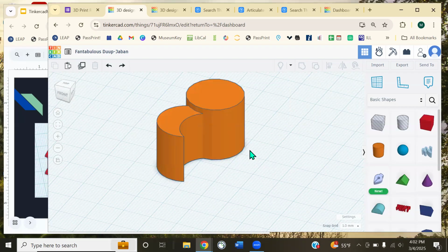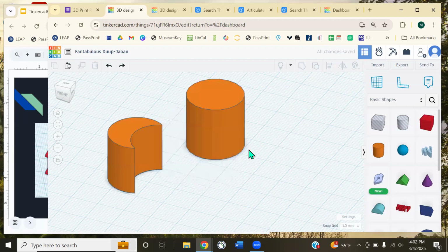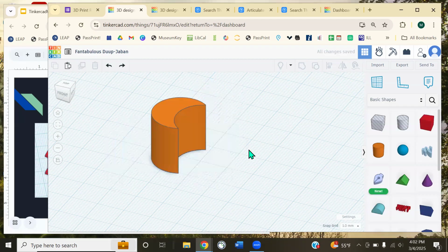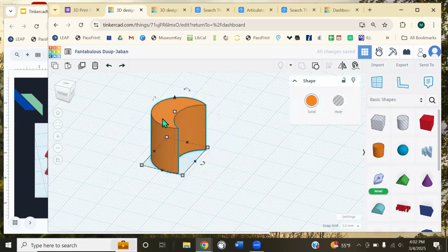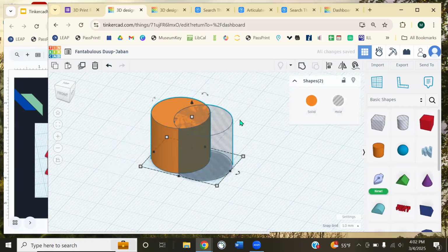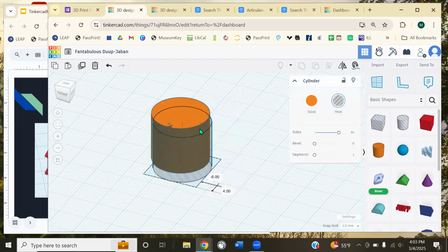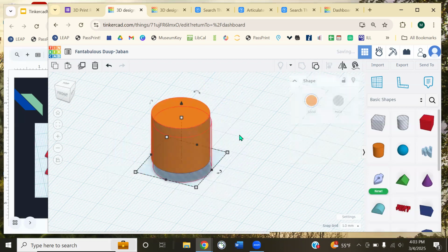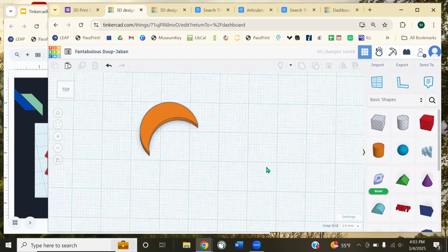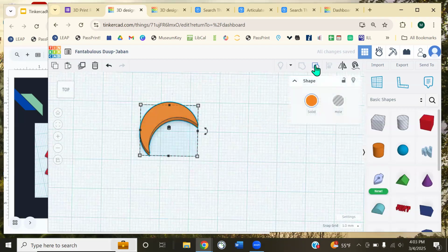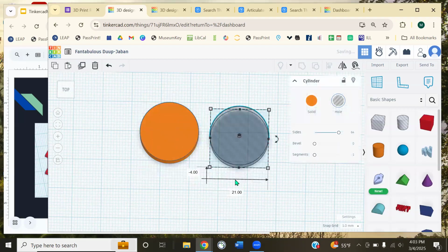I could Control Z to undo all of the steps that I just did. Or instead of doing that, I can click on this object and do the opposite. I can ungroup it, and it still keeps track of what made that grouped object. So I can undo it that way, maybe change this again and then group them again if I didn't quite like how I did it. That's how we can undo things. We can just ungroup them that way.